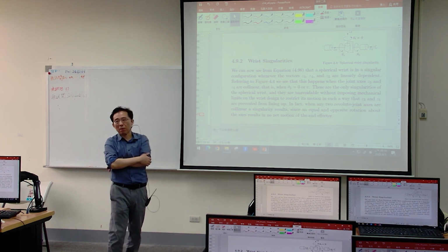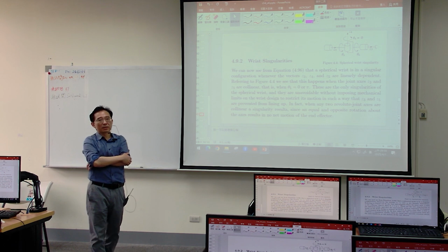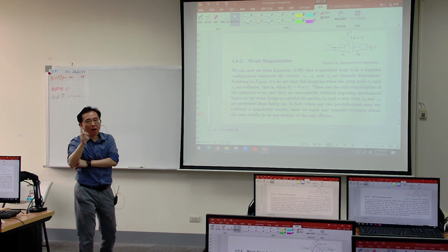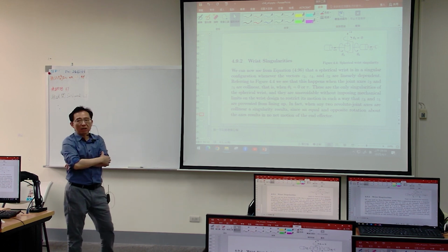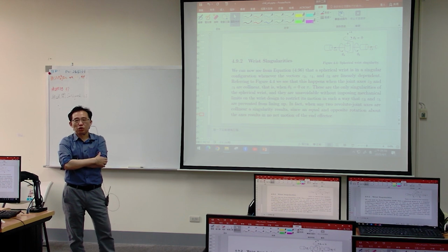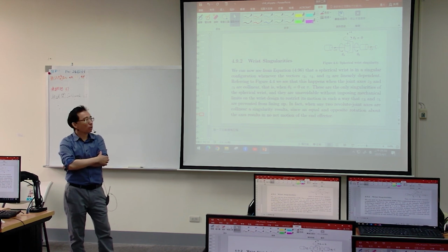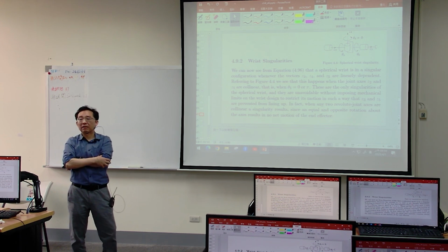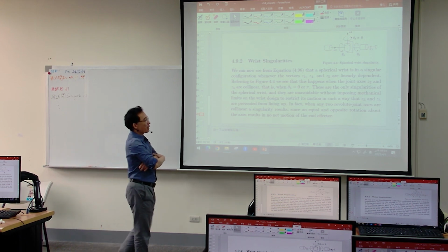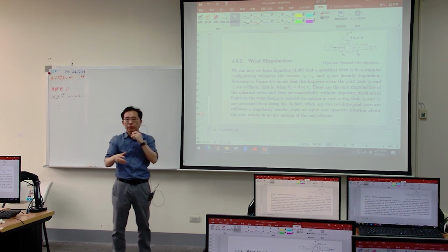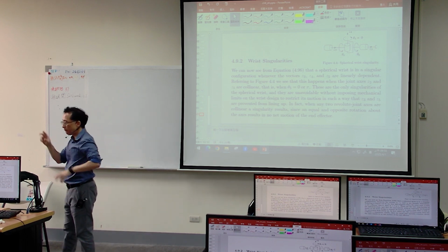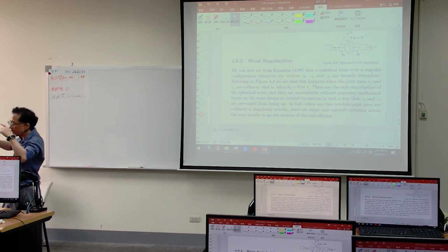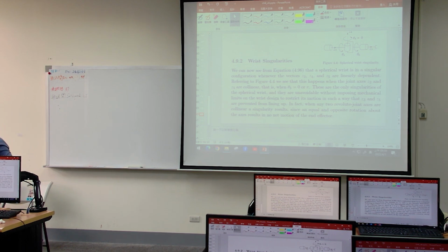They mentioned the mechanical limits. They will not allow theta 5 to jump into 0 or pi, a mechanical limit. There are also some issues we'll discuss in chapter 5. There's a mathematical issue, but for actually moving singularity issues, they can use the mechanical limit.